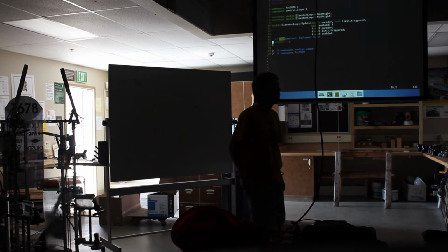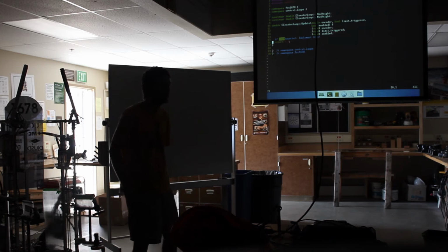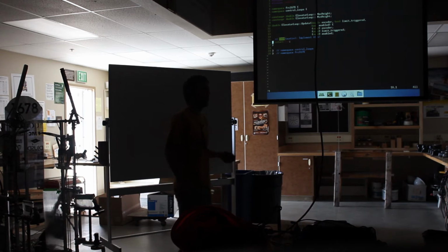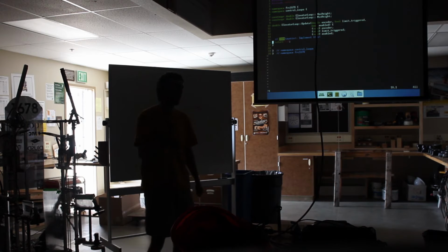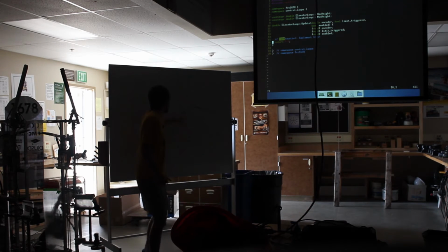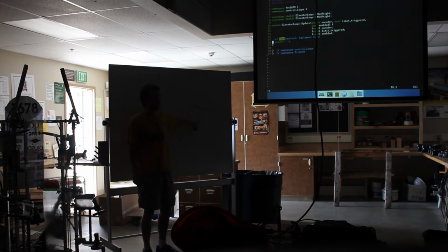How do you decide to put that zeroing procedure in the control loop versus a startup? Now I get your question. Because, at least on our robots, if it's an active zero, you can't zero till you're enabled. And what you also want is to design your software so your user can't mess it up. If the driver doesn't hit the magic set of 3 buttons to make the robot work, they don't always remember that. It's the heat of the moment. They're not going to remember to press these 3 buttons before they run the match. So what we want to do is design software that's robust to these things and doesn't let the driver screw it up. So by putting it in here, the driver can ask for whatever he wants from the joysticks, and we will not let him do anything bad.